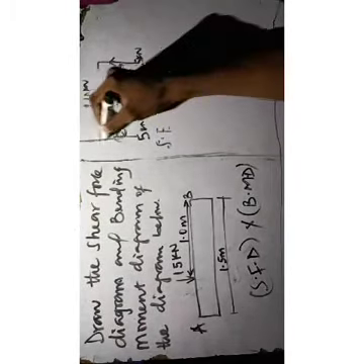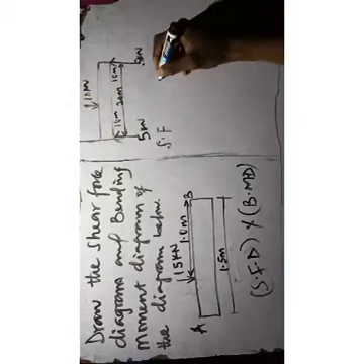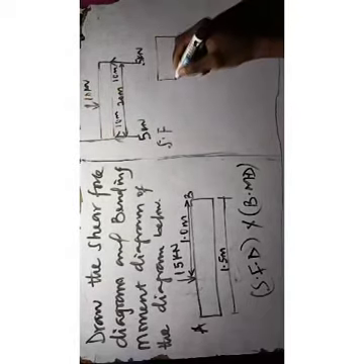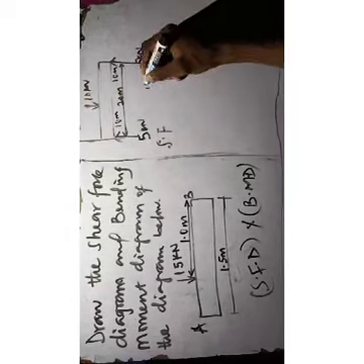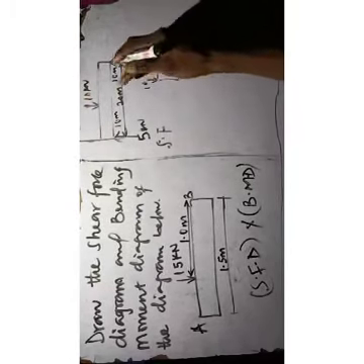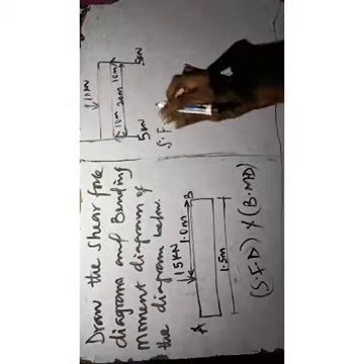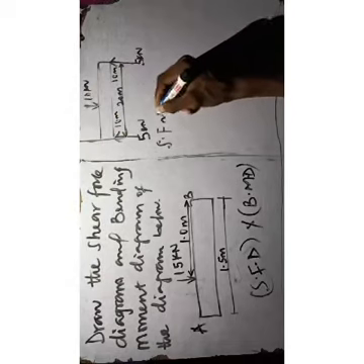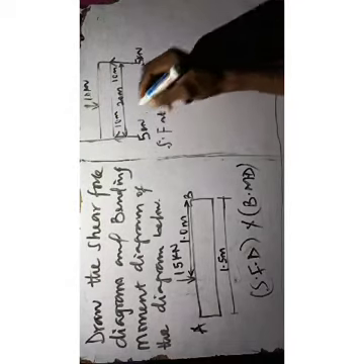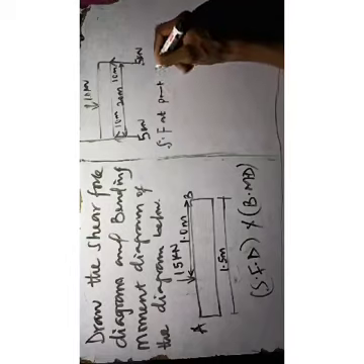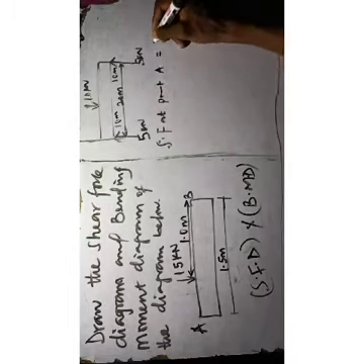So is there any force here? There's no force here. If I draw a diagram like this now, and we said maybe we calculate the force here to be 10, and I say what is the shear force? The shear force at the beginning is equivalent to the force acting on it. So here the shear force at point A is equal to 0.